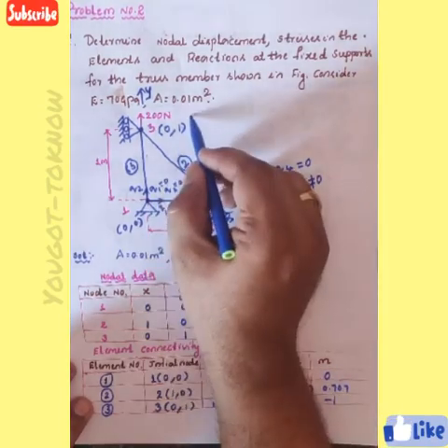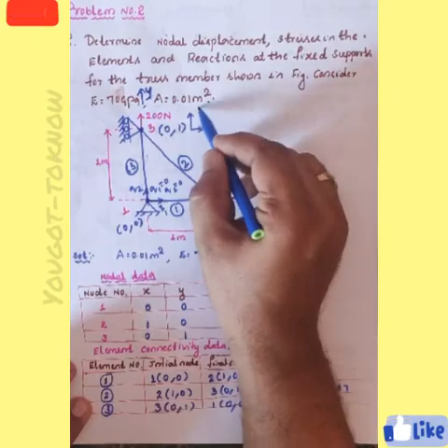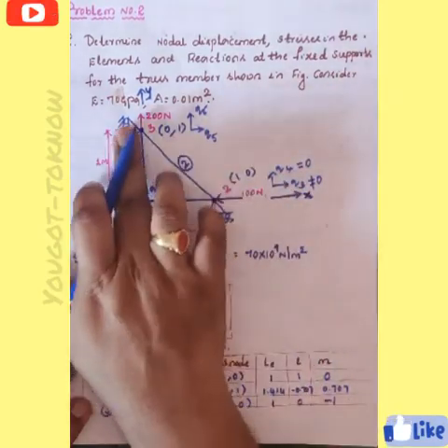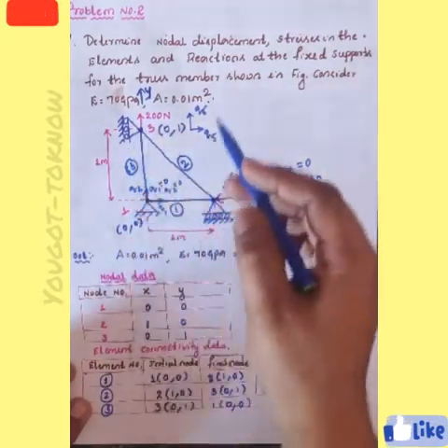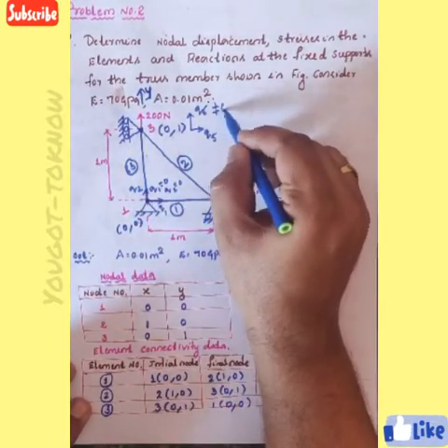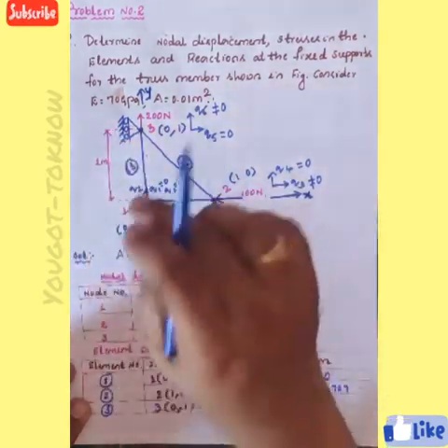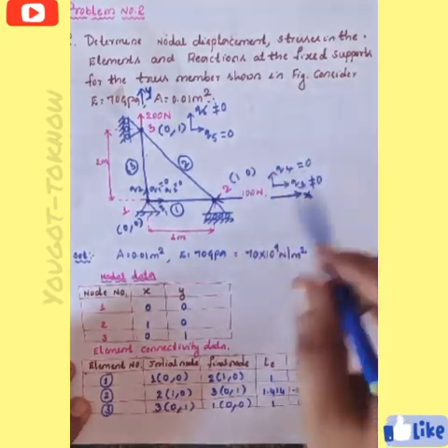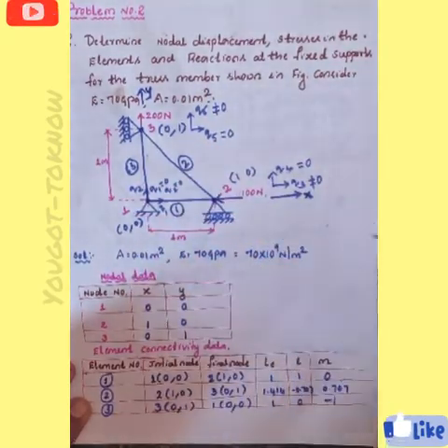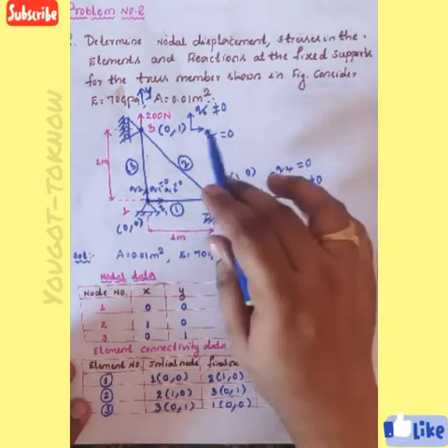Now similarly go to node 3. The displacements we represented are Q5 and Q6. The roller is given in the vertical manner, so it will travel in the upward direction. That means Q6 will not be equal to 0, but Q5 will be equal to 0 because it is fixed. When a roller is given, you should see which direction it is given and decide based on that.